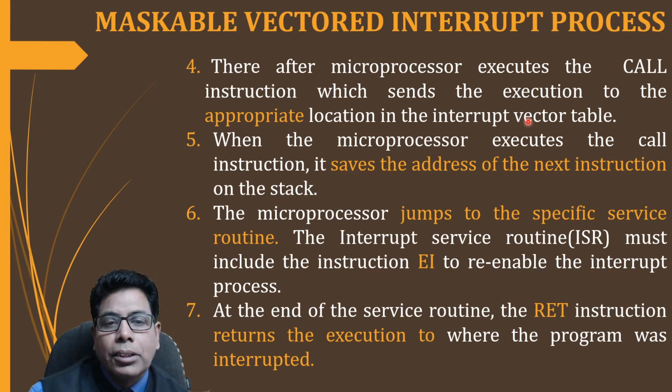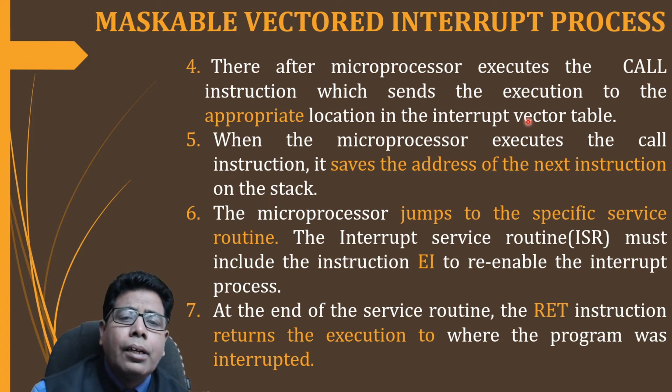Then the microprocessor jumps to the specific service routine, that is the ISR, the interrupt service routine, and it must include the instruction EI to re-enable the interrupt process. Again the ISR will have the EI instruction to re-enable the interrupt, because if the microprocessor needs to serve another interrupt, at that time the interrupt should be enabled.